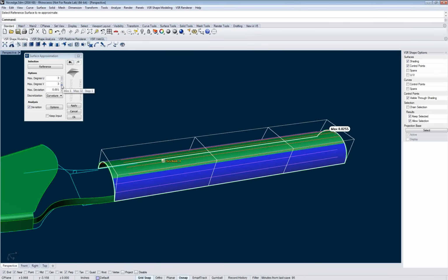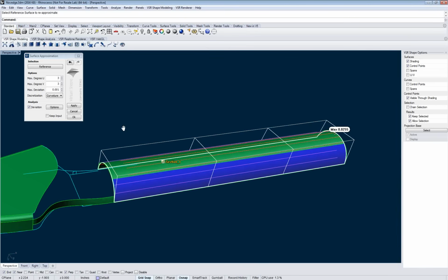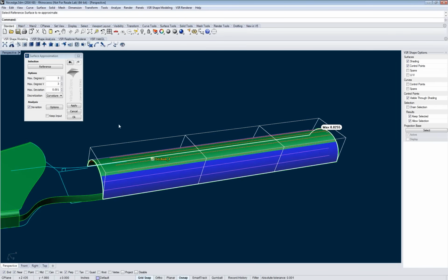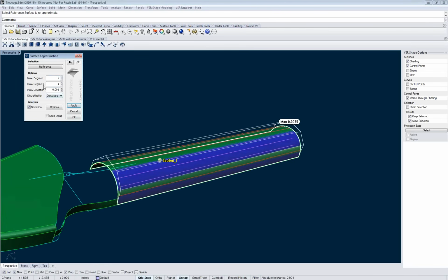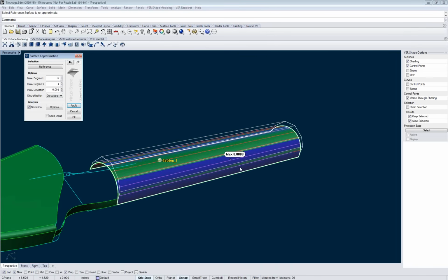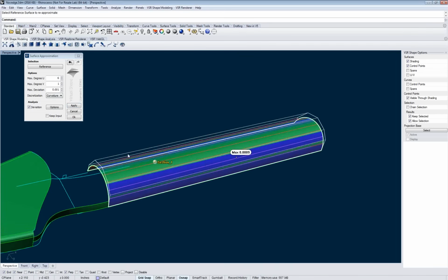I'll show something on meshes with a kind of reverse engineering in a second. Just let me finish this one, and then I'll go over to that. So you can here now reduce the number of control points and see these control points here have no influence. This part here is linear in that direction. I can now, deviation controlled, increase the order here until I'm satisfied with the result. I'm now below a thousandth of a millimeter. I got much less control points here than I had before.